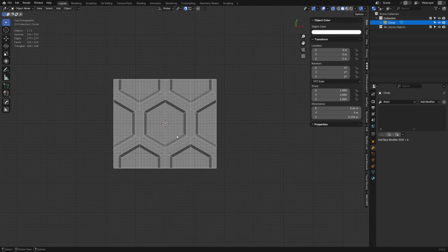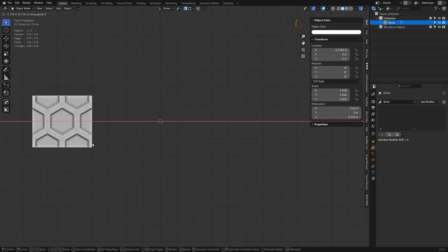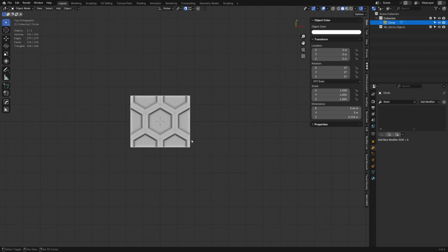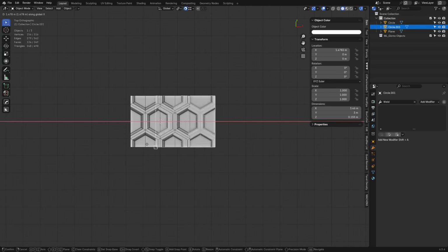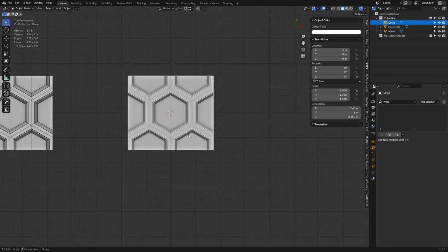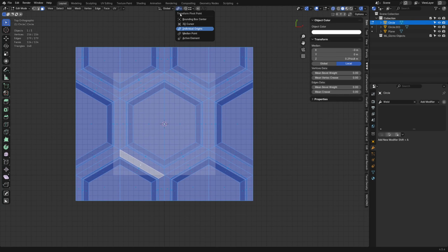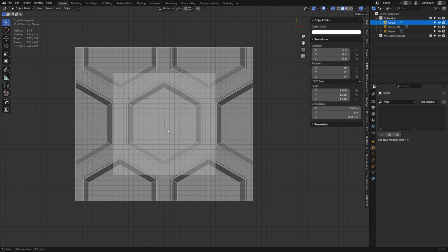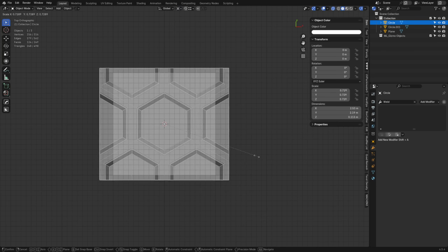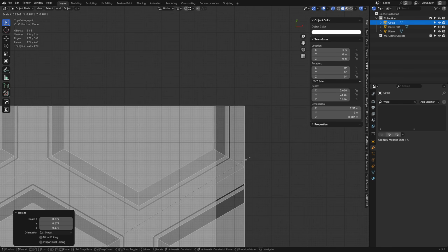The only thing is it's not in a square. So you might want to keep this one actually. You might want to use that. Create a plane. Take this and Shift, exit out real quick. I'm gonna turn that off just for a second. I'm gonna go into edit mode. We're gonna scale. Well, actually, we could do this in object mode too, but we're gonna scale using the 3D cursor. As you can see, I can just press S, scale this way.